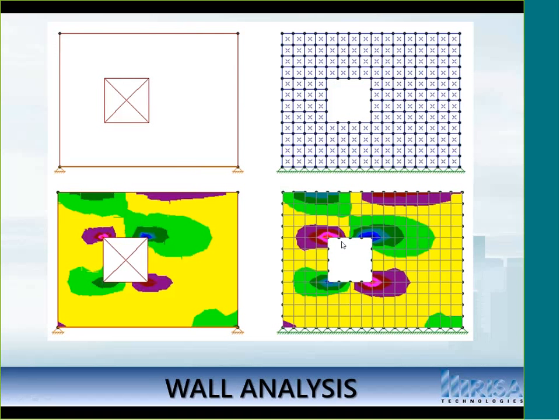So to begin with, let's just talk about wall analysis for a moment. In the most recent walls webinar, we talked about how walls compare against plates. And what you can see here is that traditionally, if I wanted to model a Masonry wall, what I would have to do is come in and model a series of plate elements, and I would have to submesh those down into a reasonably small mesh size so that I could get accurate results. By omitting plates in certain areas, that's how I would place openings. And what this would allow me to do is get forces and stresses within the plates, and then I would have to take those forces and stresses and sort of come up with a design by hand to figure out exactly what I needed.